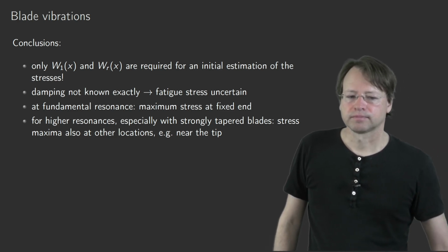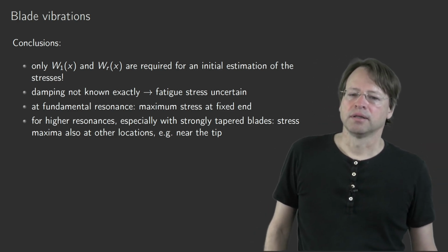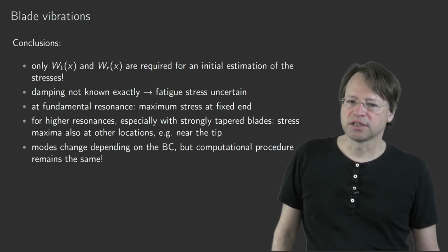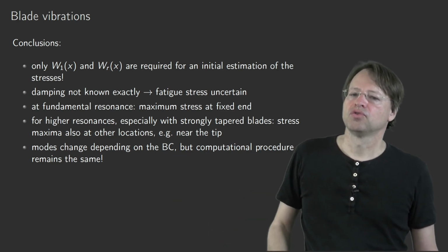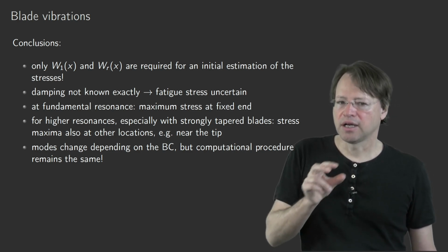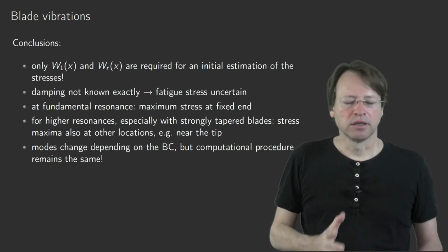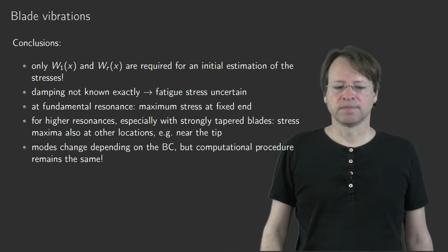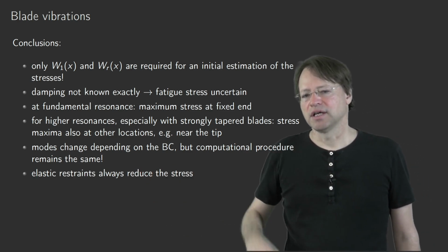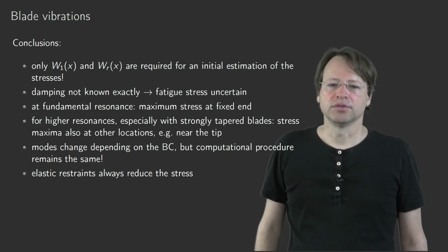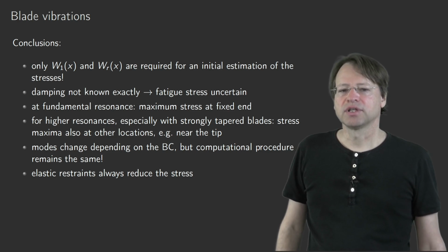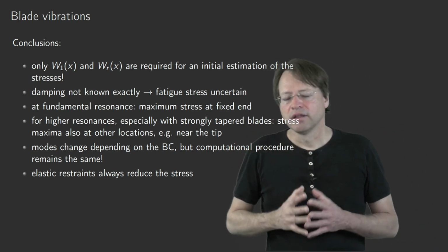Well, what else do we see? Well, as I said, the modes might change depending on the boundary conditions. The computational procedure is the same, but that could lead to maximum stresses that occur at other positions than by taking very simplified boundary conditions into account, as we did here in our analysis. So, if, for example, there are elastic restraints, then they always reduce the stress. Well, and that's all I would like to tell you already about the forced vibrations.